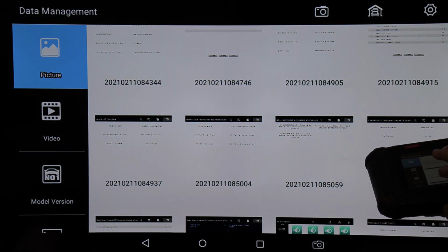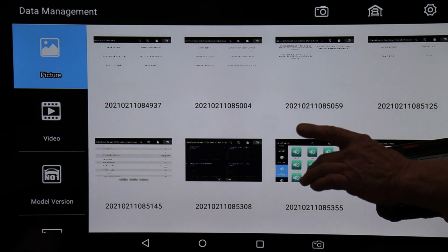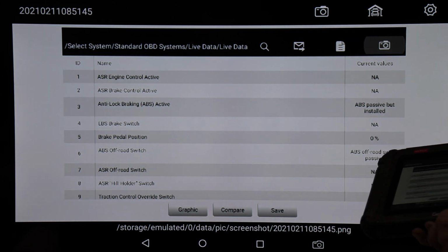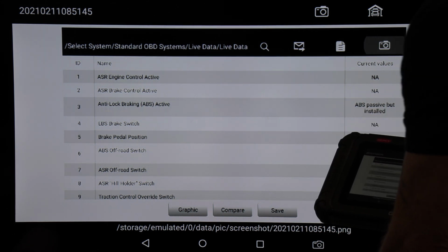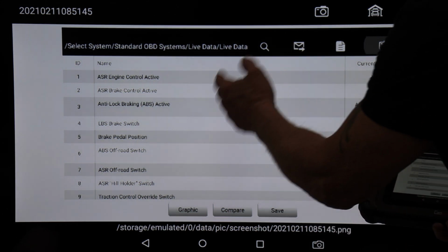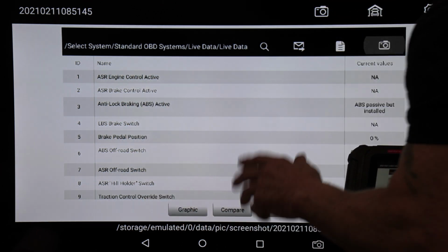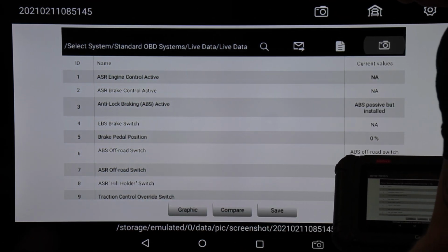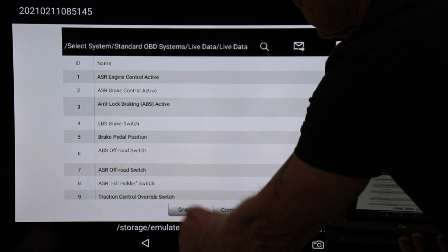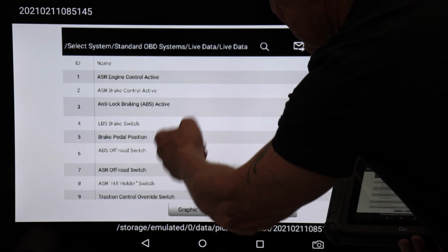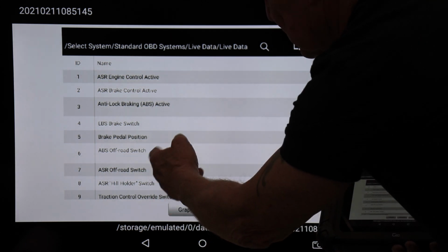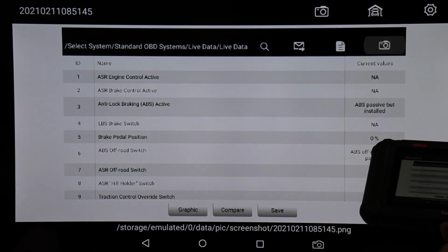So now I'm going to skip a little bit. If I went in there and I got the data, and if you notice over here, I was able to get this data. I'm still on the Kenworth side over here. I'm not in the analog brake system, but you can see all sorts of stuff here. ASR, analog braking active, brake pedal position, ABS, and so on, all right?